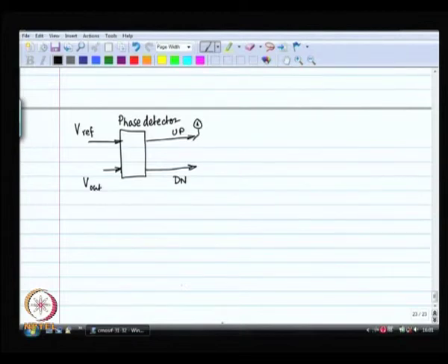And then we have got the charge pump. The simple charge pump is no good. We have to make a more sophisticated loop filter than a simple capacitor. Typically, C is going to be much larger than Cx. Cx is about a tenth. The thumb rule is keep Cx about a tenth or a fifth of C.